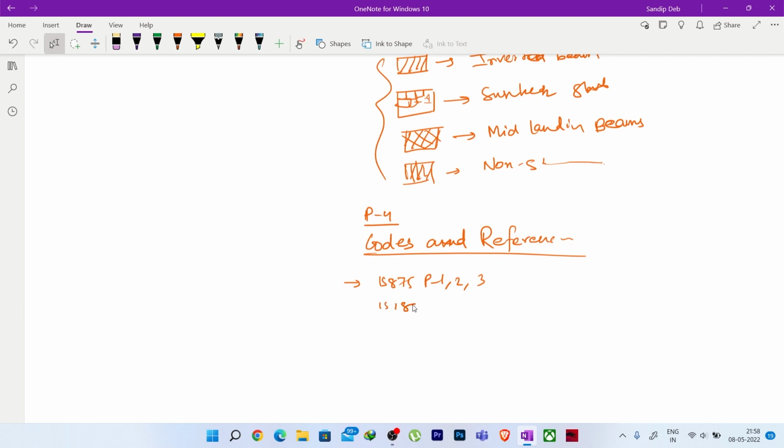You can write IS 1893 2016 part 1 for seismic load. Then you can also write maybe IS 456 2000 for design. SP 16 you can write also for design, the design handbook it is. You can write other codes also, like SP 34 for detailing of the members.